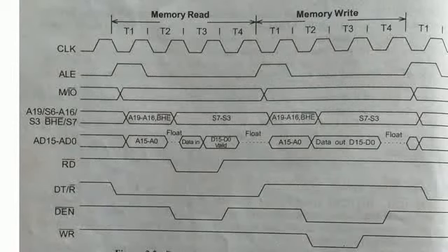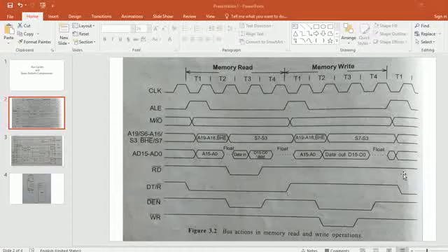Next case is when you would like to design a system using the 8086 microprocessor or any kind of microprocessor. As we have seen in the pin diagram of the microprocessor, if you want to get the functionality from the microprocessor, we are supposed to provide the required clock signal with the help of the clock pin, which, if I'm not wrong, is the 19th pin. So with the help of the 19th pin, we are providing the clock signal to the microprocessor.